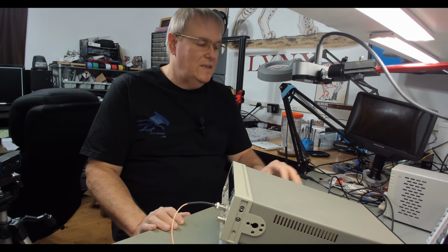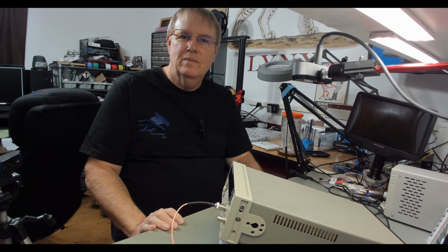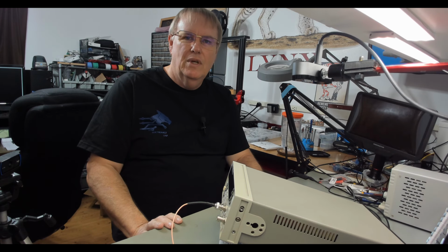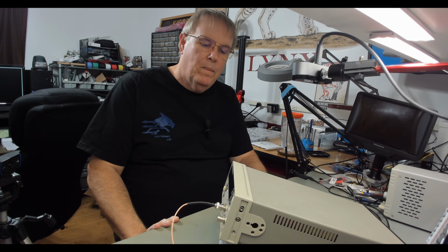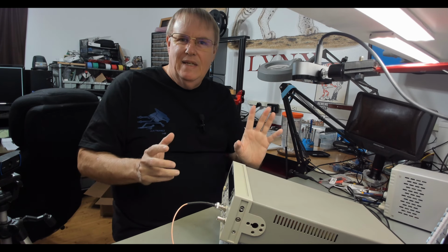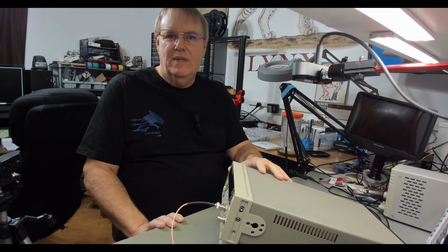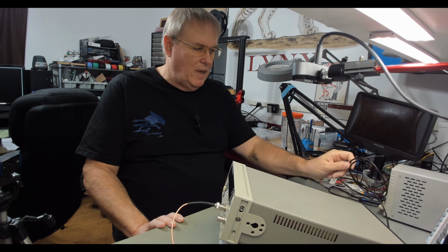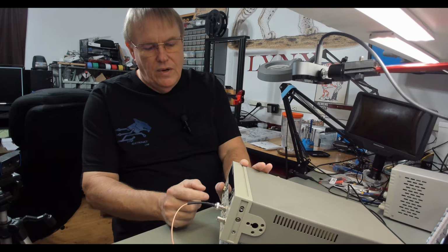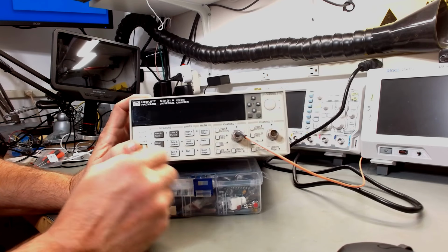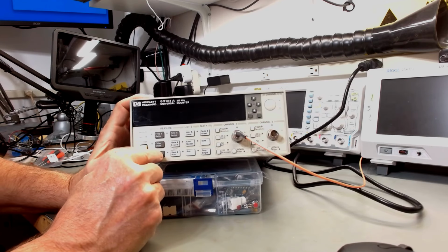And what I found was it said to use a null modem cable, the old crossover null modem cables, when you had two DTEs or two DCEs that you wanted to communicate. Well, the computer is normally the DTE, and so I assumed this must be a DTE. So I got a null modem cable and I've hooked it up. And I configured it. How you configure it, let me turn it off here, is you hold the recall button while you turn the power on.